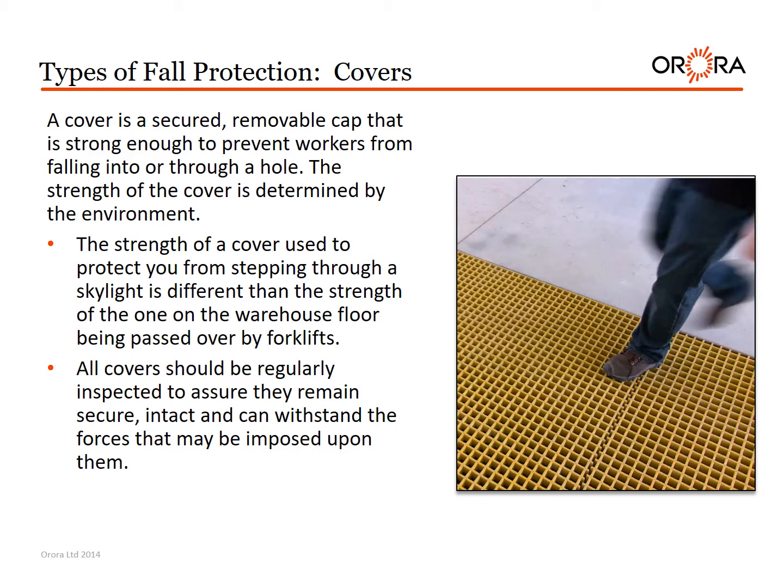The strength of a cover used to protect you from stepping through a skylight is different than the strength of one on the warehouse floor being passed over by forklifts. All covers should be regularly inspected to assure they remain secure, intact, and can withstand the forces that may be imposed upon them.